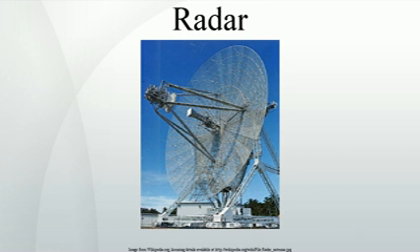Radar modulators. Modulators act to provide the waveform of the RF pulse. There are two different radar modulator designs. High-voltage switch for non-coherent keyed power oscillators. These modulators consist of a high-voltage pulse generator formed from a high-voltage supply, a pulse-forming network, and a high-voltage switch such as a thyratron. They generate short pulses of power to feed, for example, the magnetron, a special type of vacuum tube that converts DC, usually pulsed, into microwaves. This technology is known as pulsed power.